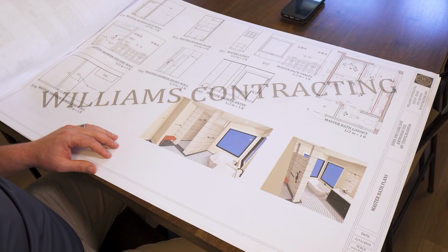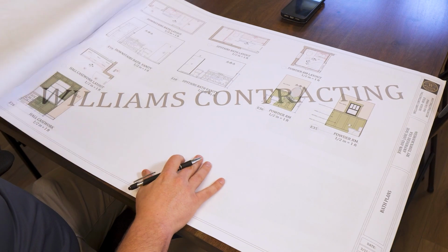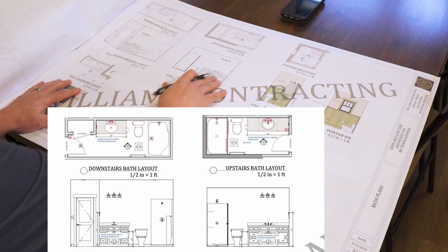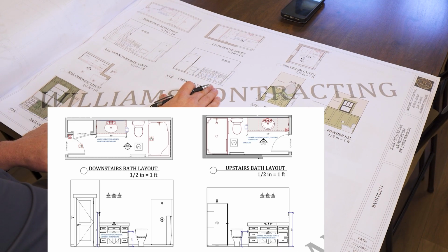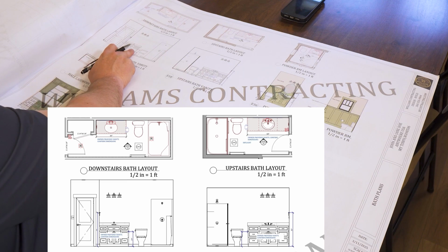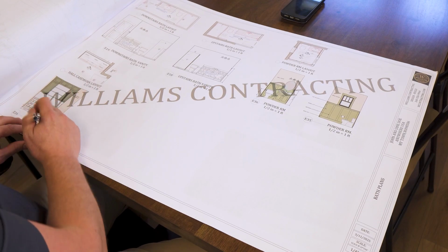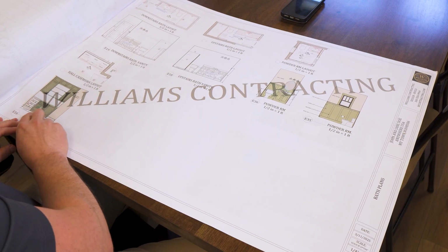Let's get into the final finish sheets for this plan. What we're going to show on this sheet is more of the bathrooms. We show the casework that's going in. This particular home was designed with pre-built vanities for these bathrooms. So we call that out as owned and provided, confirmed dimensions. But we have a hallway casework that's going in down here. We show a wine fridge, some cabinetry, some glass shelf call out.